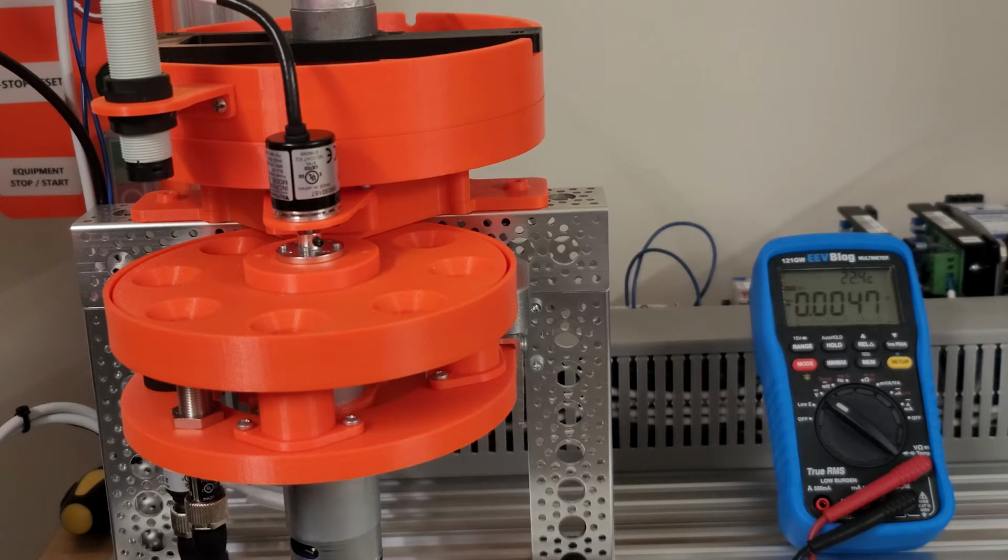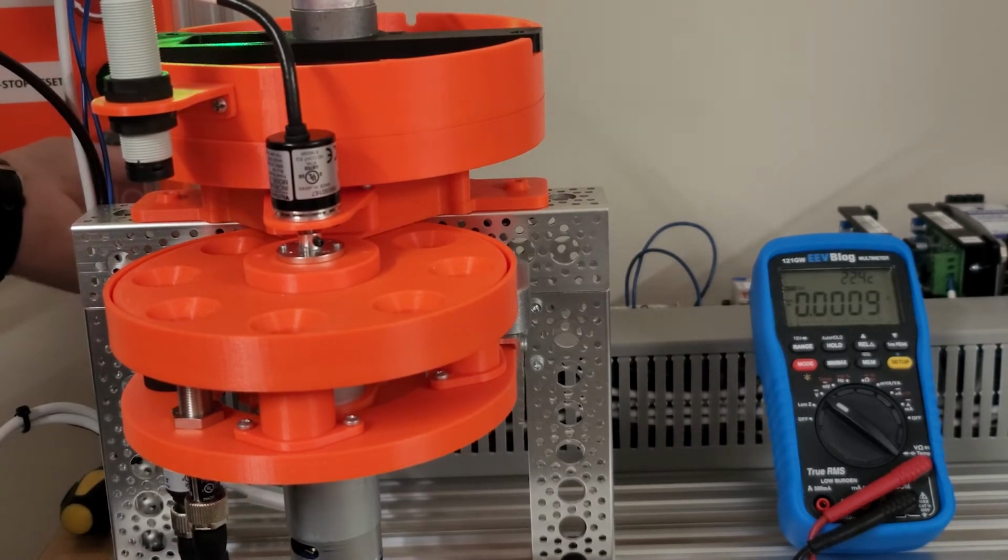So I'm going to verify what voltages we're getting out of the thing. I'm going to check the analog output of the I/O card to see what our voltage is, and I'm also going to be checking the voltage that's coming out of the drive going directly into each of the motors to make sure it's relatively half of what we expect, the maximum being 12 volts, so the half should be 6 volts. So it should be relatively easy to see. So I'm going to go ahead and start it. Again, apologies for the noise today, but here we go.